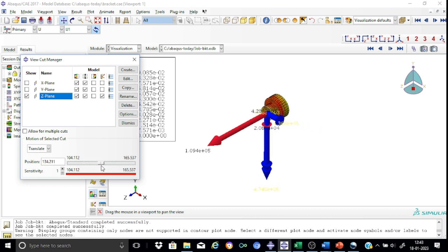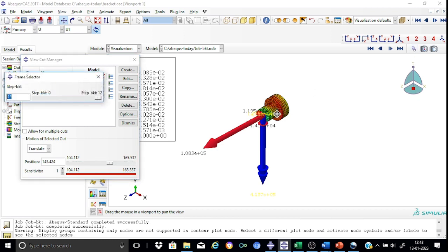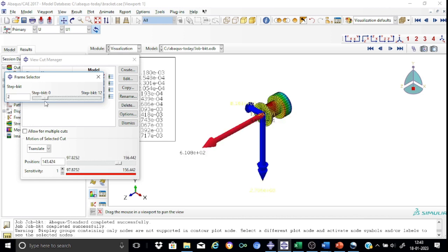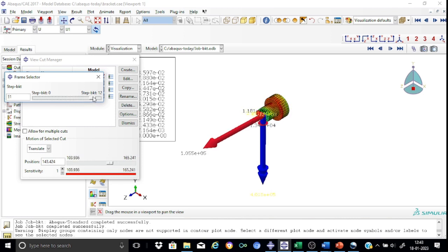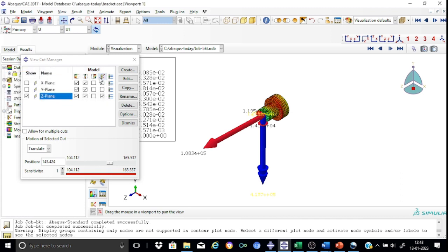We find that the shank is subjected to a constant force of around 110 kilonewton. You can also obtain the force in the bolt at any time frame. If you start from the zero frame, you will find that it is increasing to say 71, 83, 94, 110, etc.